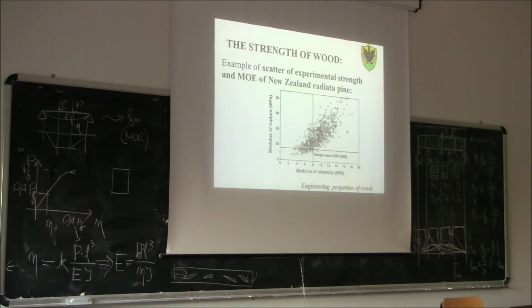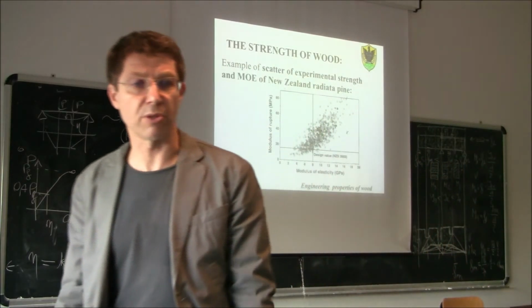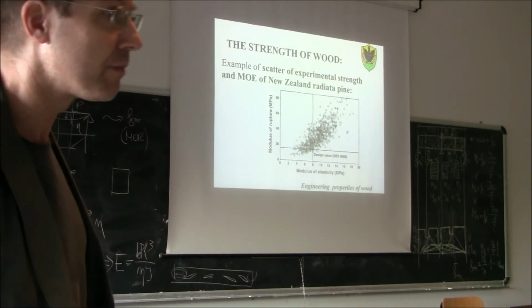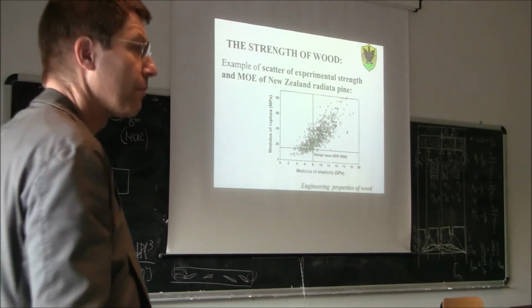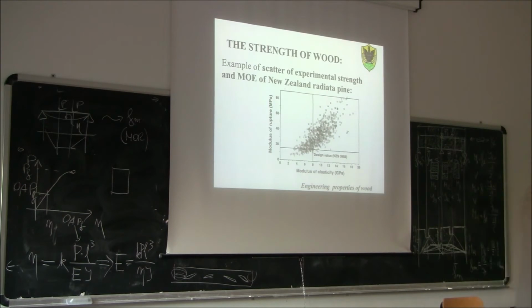Which value of modulus of elasticity should I be using? Also here we need to remember what we need a modulus of elasticity for. You told me before, modulus of elasticity is needed for, can you repeat please? Limit state of serviceability. Of serviceability limit state. Now for serviceability limit state, if you remember, we said that in this case our, let's call it design value, is which value? The minimum value. It's the mean value.